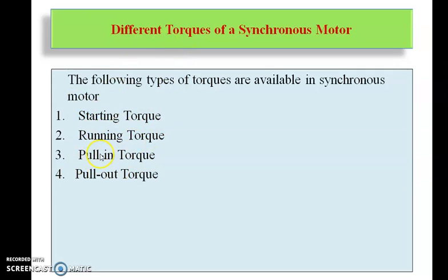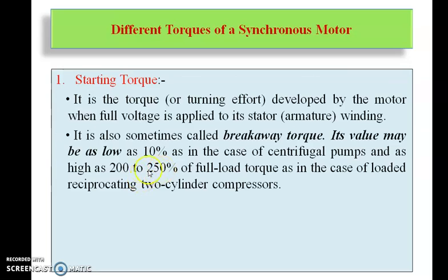Starting torque, running torque, pull-in torque, pull-out torque. So we will see one by one. Starting torque is the torque or turning effort developed by the motor when full voltage is applied to the stator winding. Starting means the initial torque. It is the torque or turning effort developed by the motor when full voltage is applied to the stator or armature winding. It is also sometimes called a breakaway torque.